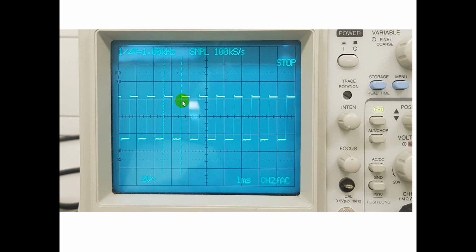So what we have here is one time period, and obviously I think it will take one box here, most probably. So this one box multiplied by my time scale, which is 1 millisecond, gives 1 millisecond as my time period, and the frequency will be equal to 1 divided by 1 millisecond, which is 1 kilohertz, which is shown here. Delta t is 1 millisecond basically. That's why I get a 1 kilohertz signal. So it means the input we are given is basically 1 kilohertz.